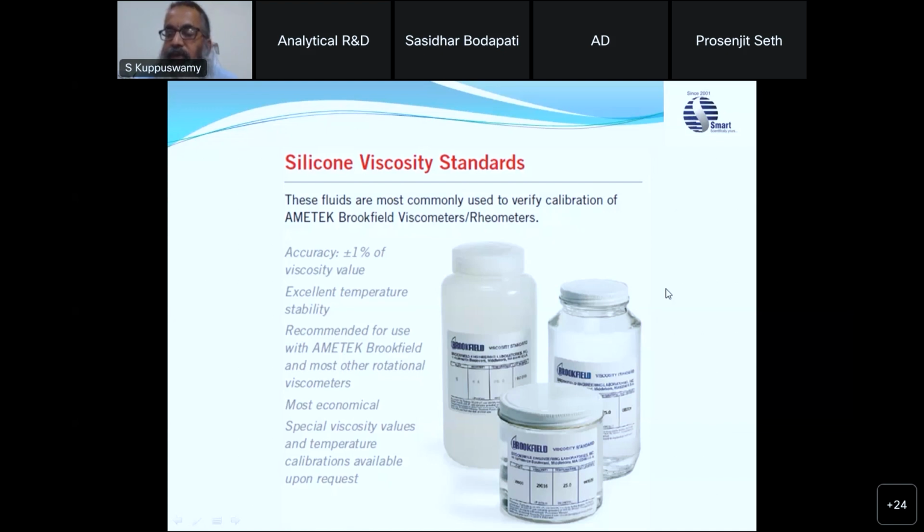Yes, sir. Related to gelatin strength, if you want to measure it later once the gel is prepared, if you want to know the polymer gelatin strength, as per the GME and GMIA standards, we have a texture analyzer with Bloom strength to measure the gelatin strength, particularly designed for texture, cohesiveness and adhesiveness of the sample.